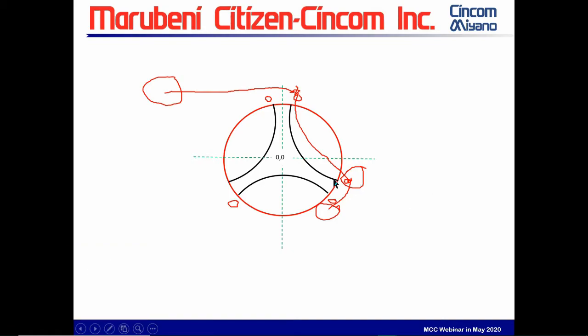The radius here is bigger. Going center of the radius of the tool to the center of the radius of the tool is much longer and bigger than this short little radius being generated here, if you're going to do that. So the feed rate will be based off of this, which if you want this to go at 10, this would have to go at 35 to be able to generate that at the proper feed rate.